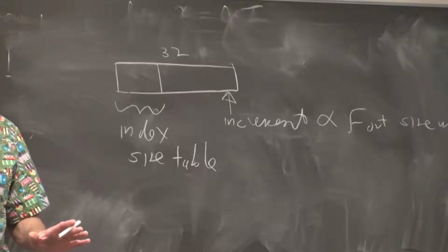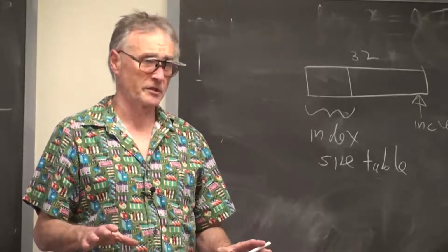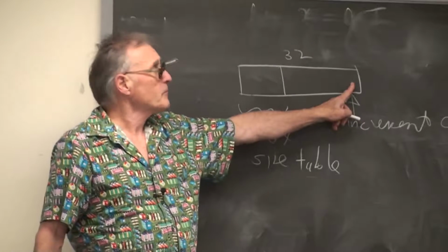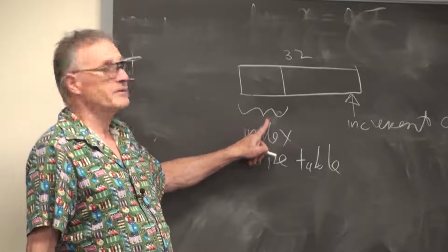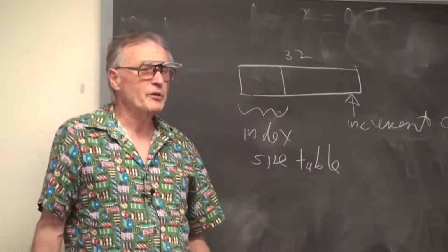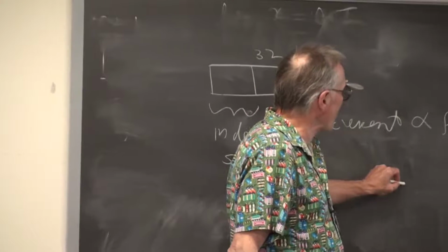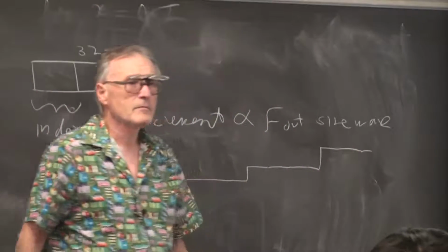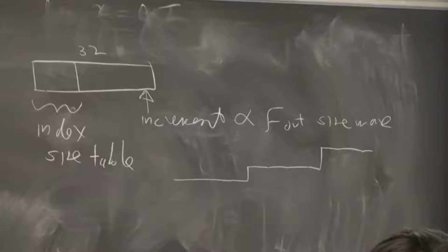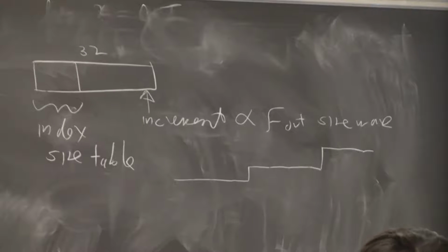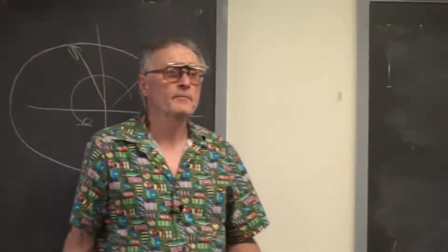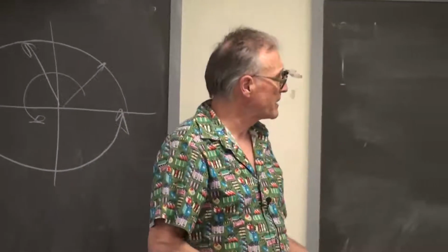This has a couple of implications. One is that if I'm asking for a very low frequency, since I'm incrementing down here at the low end of this variable, there are 24 bits before we change something that's related to the table. At very small increments, I might put out the same value for several sample times in a row, and then step up to the next sample and then to the next sample. That's okay, because it's still going to be the case that for one whole cycle you have 256 different values, and you can show that the first major Fourier error term is up at about the sample frequency.